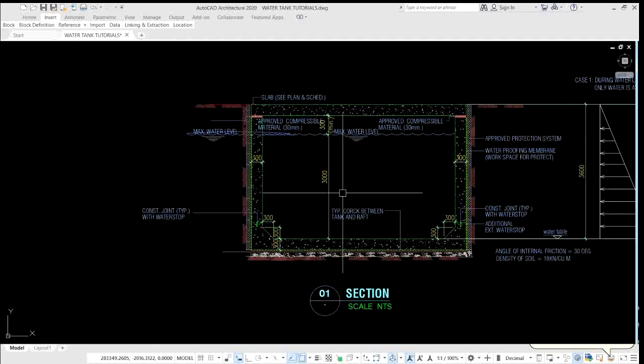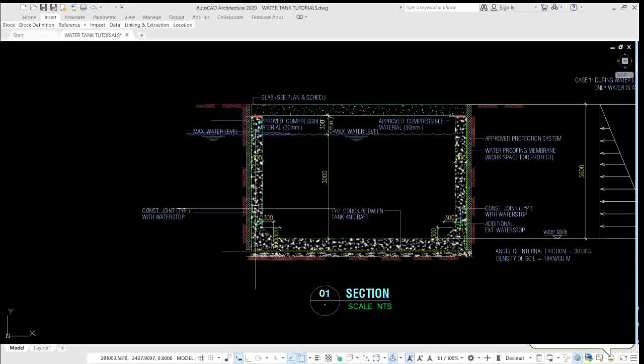At the surface, we have two main forces acting on the wall. One is the water, and second is the presence of the earth, or the earth pressure, plus, if there is a surcharge load on top of it, you may add it to your solution.